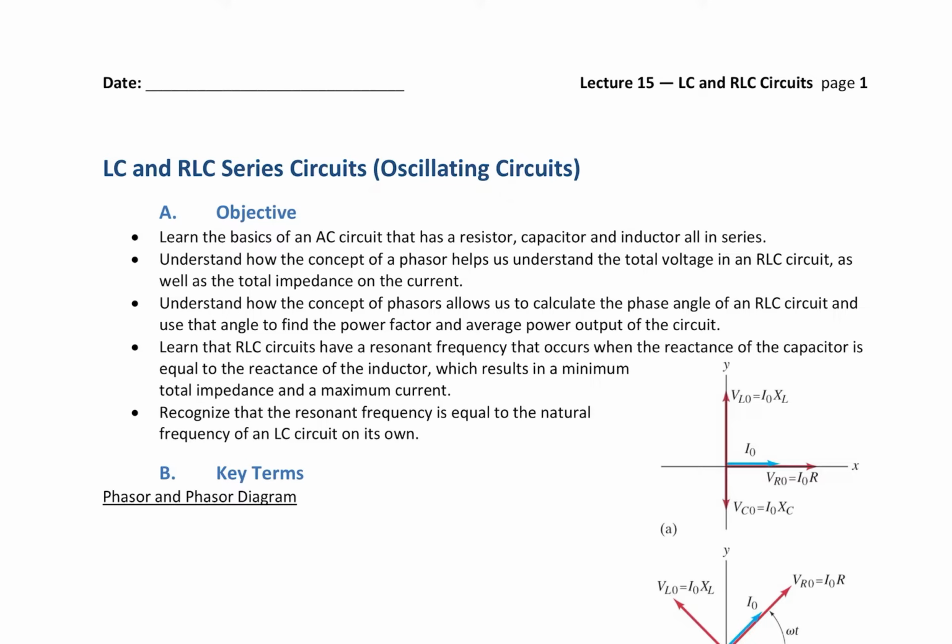So we have a few objectives here. I want us to learn the basics of an AC circuit that has a resistor, capacitor, and inductor all in series. Furthermore, we want to understand how the concept of a phasor helps us understand the total voltage in an RLC circuit, as well as the total impedance, a term we'll introduce, on the current. We want to understand how the concept of phasors allows us to calculate the phase angle of an RLC circuit and use that angle to find the power factor and thus the average power output of that circuit.